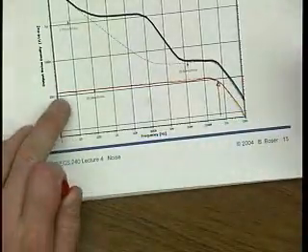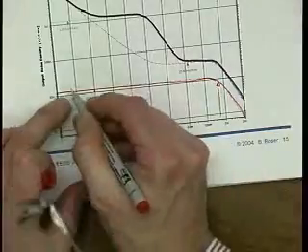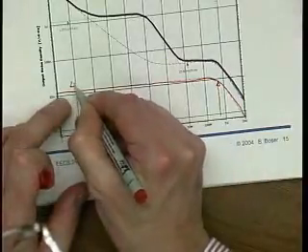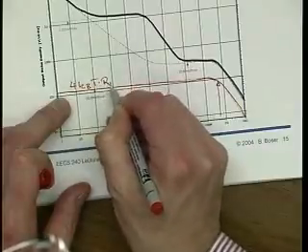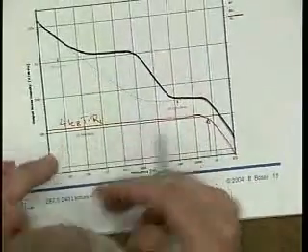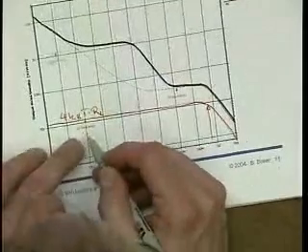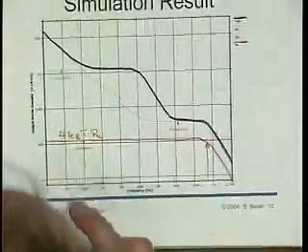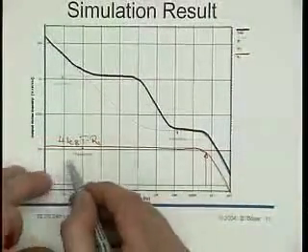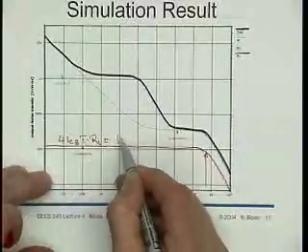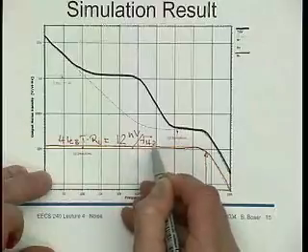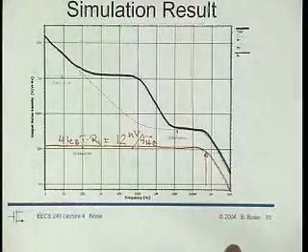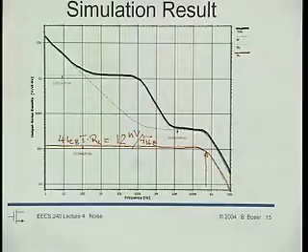And now, of course, we can calculate 4kBT times RL, which is 10k ohm, and take the square root, and I've done that, and I got something like 12 nanovolts per root hertz. And SPICE, not too surprisingly, agrees with that, right?